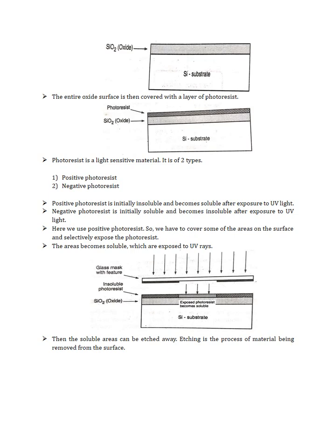After that, the photolithography steps will start, which is the application of photoresist. It can be positive or negative. Depending on that, the mask will be used. It will be exposed through radiations, and here ultraviolet rays have been shown in the figure, where the pattern is being exposed through the mask onto the photoresist. This photoresist is then developed, and after developing, the process of etching removes the unwanted silicon dioxide from the desired window.